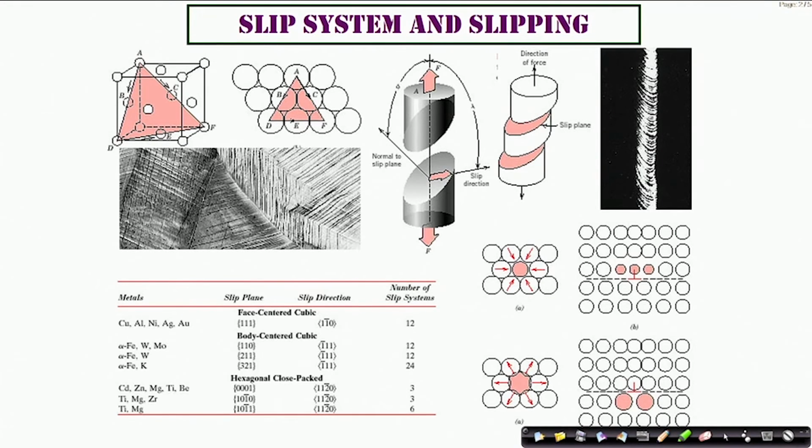It requires a lesser amount of shear stress compared to a situation where the crystal is all perfect. So the defects have a role to play not only in defining the stability but also in defining certain characteristics, deformation behavior, or in general the bulk or surface properties of the crystal.